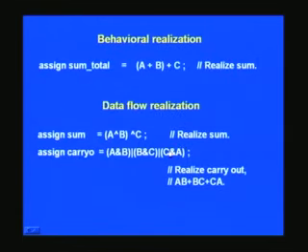So, there are three ways of implementation of the same full adder, and one we have already seen at the earlier stage, that is the behavioral level of realization. Suppose you can just put a simple arithmetic expression such as (a plus b) and c, and this parenthesis is only to guide the synthesis tool to make it very efficient. If you do not put this, it may infer internally 2 mux and so on. Instead of that, only 1 mux will be put if you guide the synthesis tool as such. That is why it is a good habit to use parenthesis freely, right.